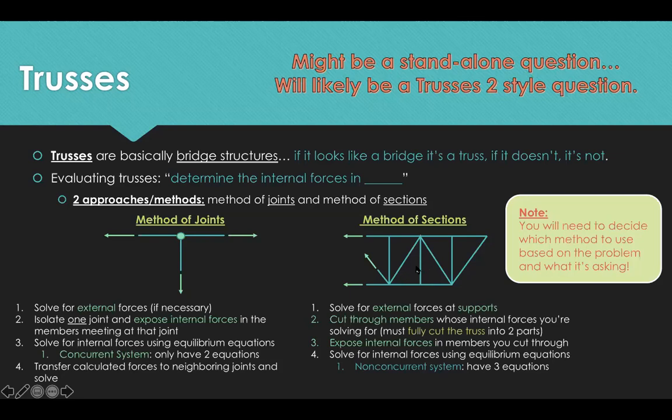Yeah, it does. All right. Anyone have questions? If there's a force on that joint you were just pointing out, like pushing down from the top, would that not affect it at all? Like if there's a force on that member, but it's not specifically on that joint. Right, so that's exactly true. If there is a force pushing down on this top piece right here, it would not affect this joint, because if there's nothing on this joint, then this is a zero force member. So essentially all that would mean is that this force that's hanging down here is acting 100% through this and this member. None of it actually makes it through this member.